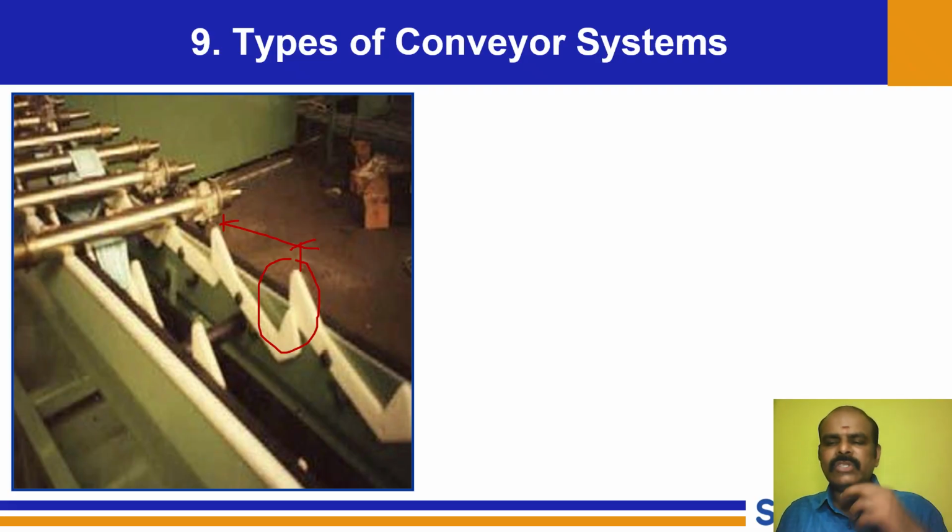So usually it is used in two cases. Case number one, when you want to machine, the operator should load and unload. At some prescribed distance or prescribed time, within that particular gap, if they get the part, that is sufficient. Under those cases we go for a walking beam. Or other cases, in painting, some exposure is necessary for the part for a prolonged time. So you can adjust the pitch and therefore we can design accordingly.